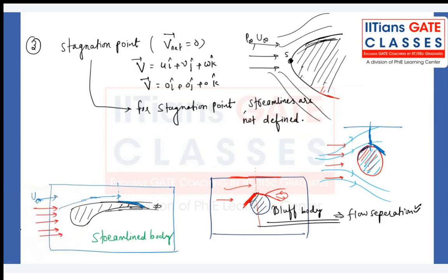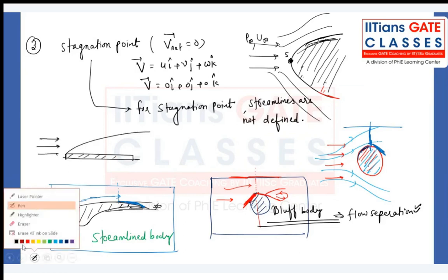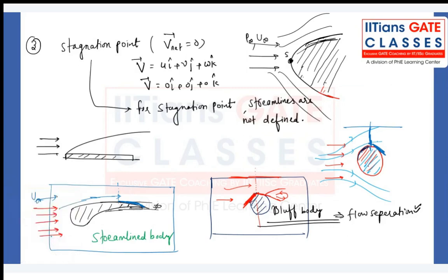And for the flow over the flat plate, whenever the fluid is flowing over the flat plate, is any flow suppression possible? Have you ever thought of that? Never possible. It is not possible because dp by dx is always zero. Pressure will always be atmospheric pressure.